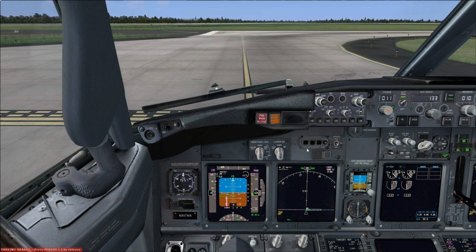And you find yourself in the downdraft, you lost the headwind, and you could potentially end up even below the minimum speed at which you're safe to fly, and you could again stall, and combine that with a downdraft pushing the aircraft down. Again, you can see where that would go.